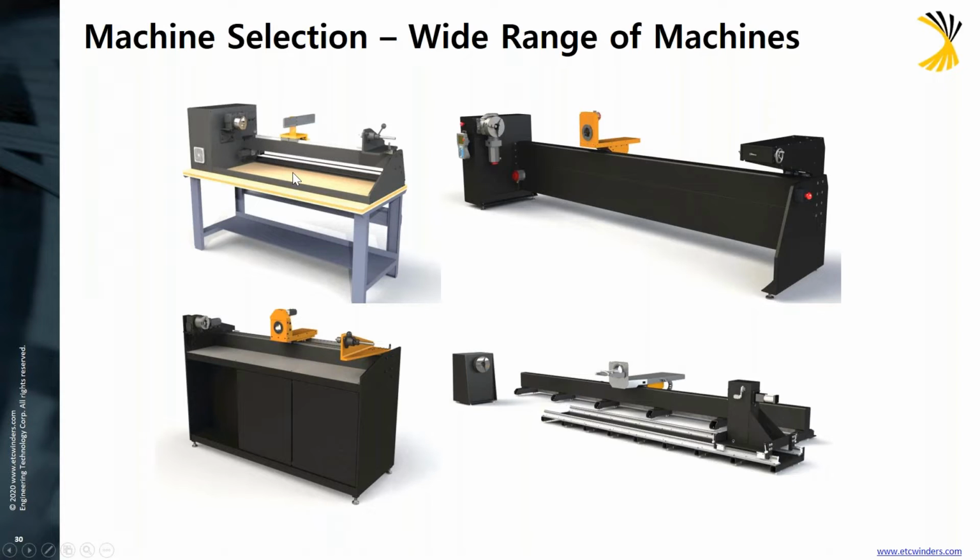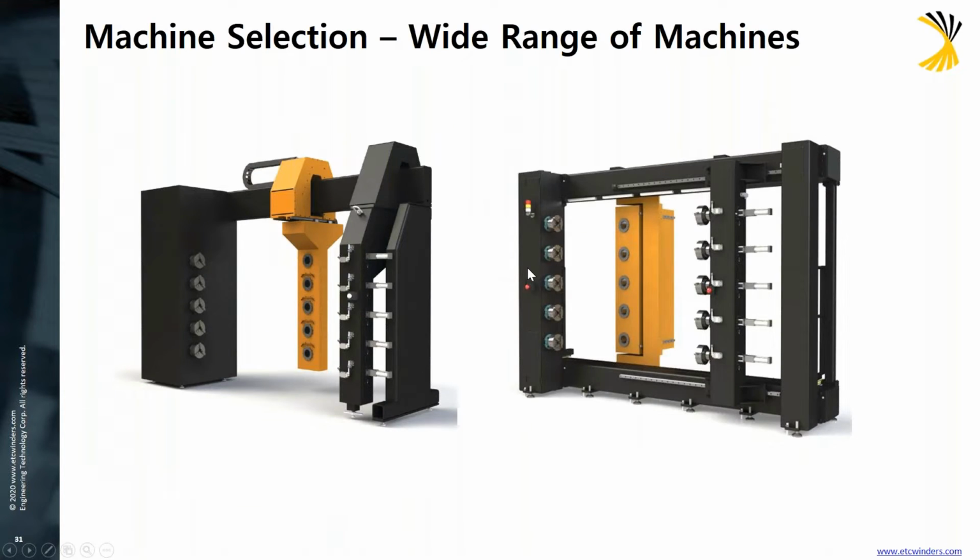In the market, there are small 2-axis machines that will wind small parts and do test samples. And then there are large scale machines. This one in particular will run 60 to 100 tows, has a 10-inch rotating eye, and can handle a mandrel up to about 20,000 pounds. So a lot of different options with machinery. All these options that we're looking at right now are actually standard options, which means that their costs are a little bit lower, as long as their parameters fit within your part anyway.